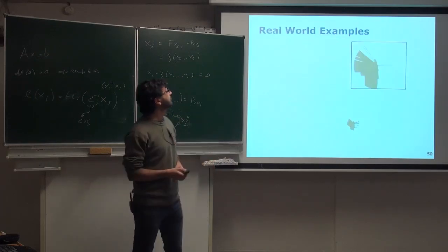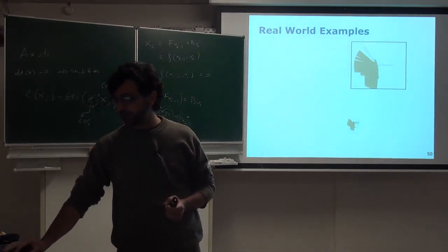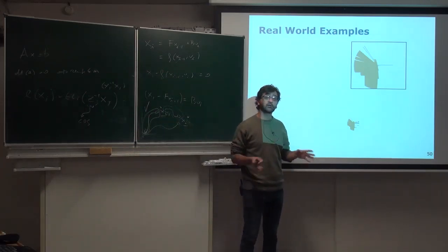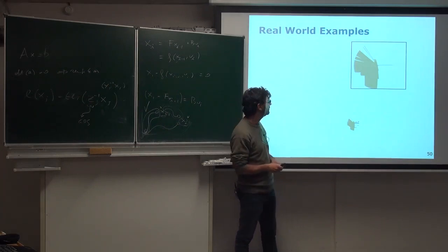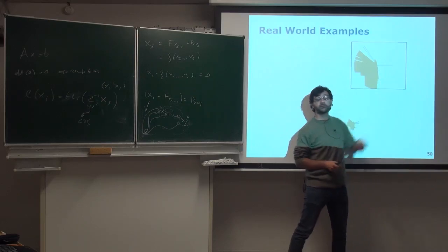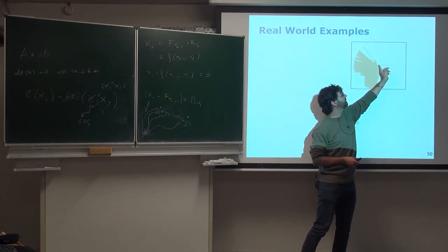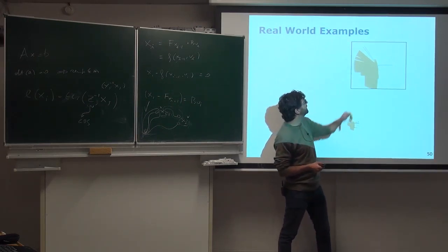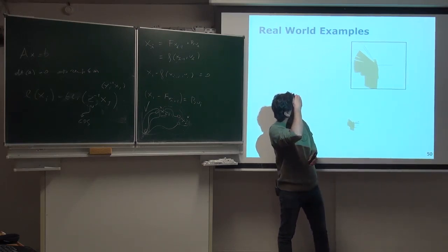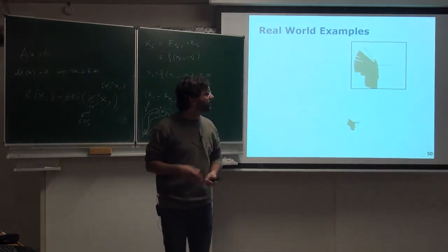Okay, so I will show you now a real-world example of using a graph-based SLAM approach. Here you will see the full spectrum, so front end and back end at the same time. It is using a laser scanner. Here in blue you see the graph built so far. So basically there are a lot of nodes and edges between those nodes. You can see slightly here in black the map built. So we do a rendering using mapping with known poses on the fly.